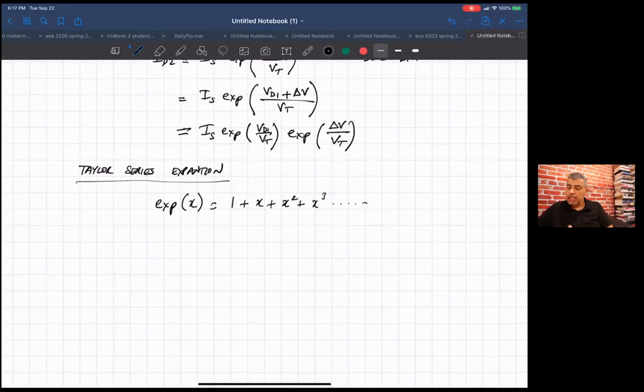Then what we're going to say is, let's do a Taylor series expansion of this guy. This first term is easy, we know it: it's ID1, I sub S exponential of VD1 over VT.